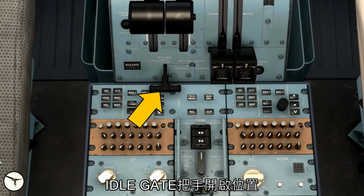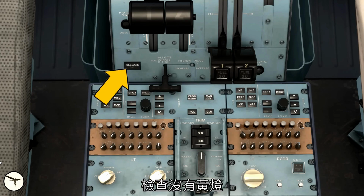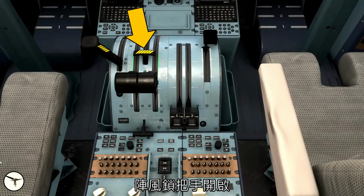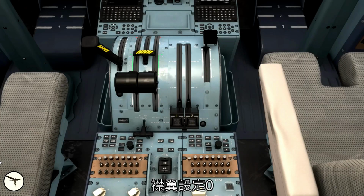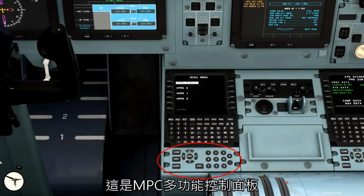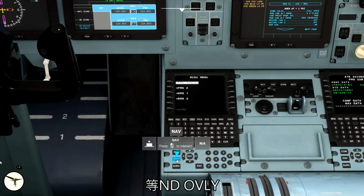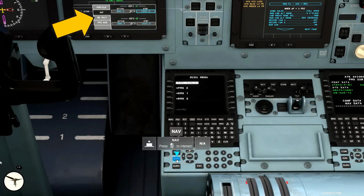The idle gate lever is checked in open position, there should be no amber light. The emergency audio cancel switch is guarded. Gust lock lever is on, flap set to 0. This is the MPC multifunction control panel. We press the now push button until we see now overlay.